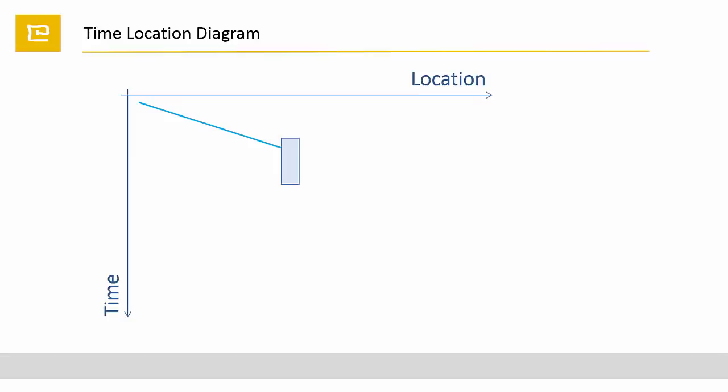Then you have some possibilities that can be displayed and explained very nice in a time-location diagram. You may stop the linear activity and wait till the local construction is finished. You may jump over the local construction and come back later to this area. And finally, you may move the whole equipment and do the rest of the line from the other direction.